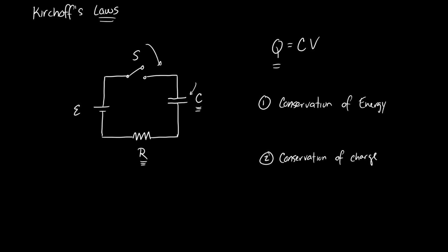So what that would mean in our circuit is a single loop, right? You understand, right? There's just one loop there. But if you were to start, say, here, and progress through the circuit, the sum of the voltage drops across all the elements in the circuit equals 0.